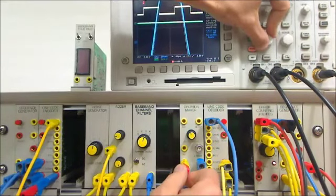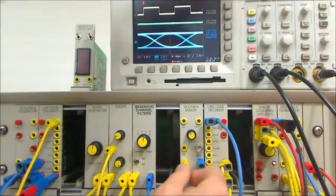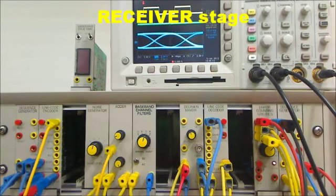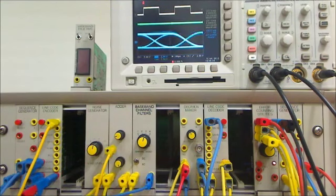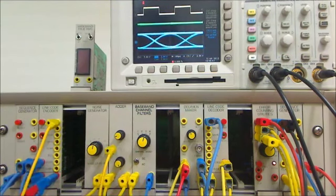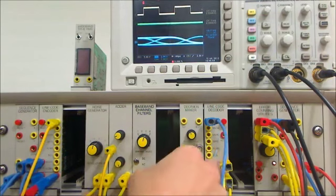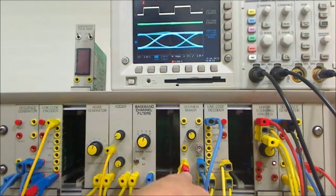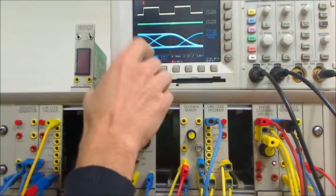Have a look at the input to the decision maker. Just channel 2, looking at the input of the decision maker. This is an amplified version of the signal from the baseband channel filter. We use this amplifier to control the level of the input signal to the decision maker so that it is set to the preferred input level of plus 2 volts peak, which is 4 volts peak to peak according to the user manual.